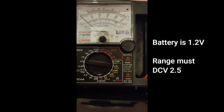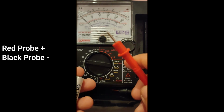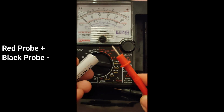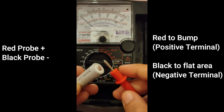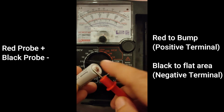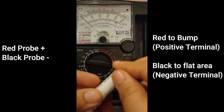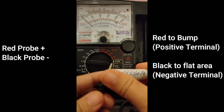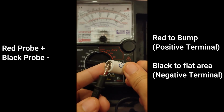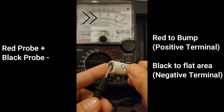Okay? Next, after setting the range, you are going to put the red test probe or the positive probe to the bump of the battery. Here is the bump of the battery. And the black probe or the negative probe, you are going to put at the flat area of the battery. See? The pointer fluctuates if you put the test probes to the terminals of the battery.